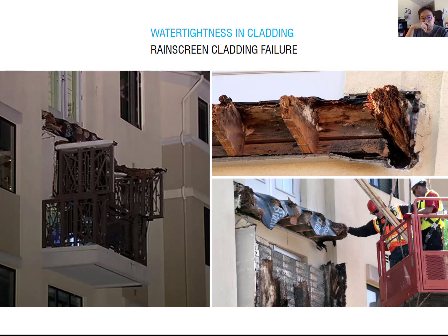So that's one main reason, but also this structure was getting weaker. Usually when you see these types of beams, mostly they are exposed, so when they get wet, it's very easy to dry out. But in this detail, everything is captured by the finished material. So when water comes in, the water never gets out of the space, and there is no air space between the structure and the finished material.